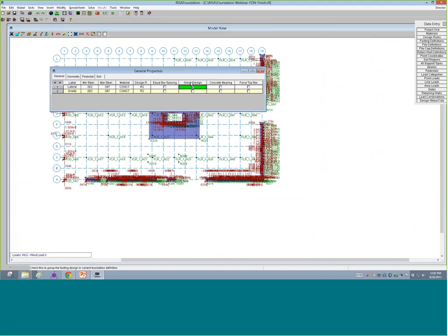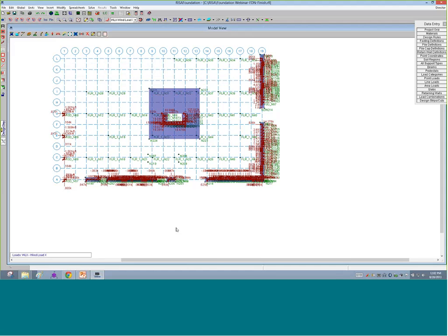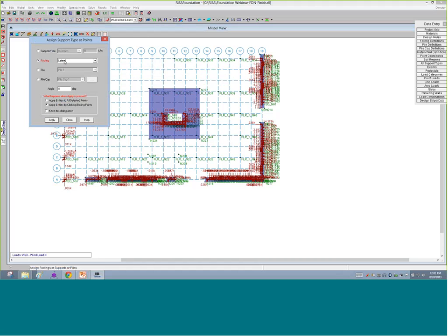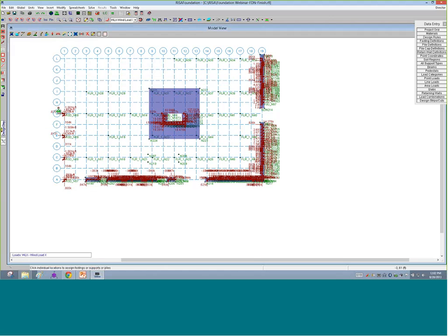So I'm going to say, hey, all the lateral ones, make them the same, because I want to have some similar footings, and that way it's quick and easy to say, okay, under all those moment frames, those are going to be those lateral footings. The rest, just make those all the same. So when we're drawing our footing, we can say, okay, just these will be the lateral ones, and I can box that area, and that will be showing up like that.